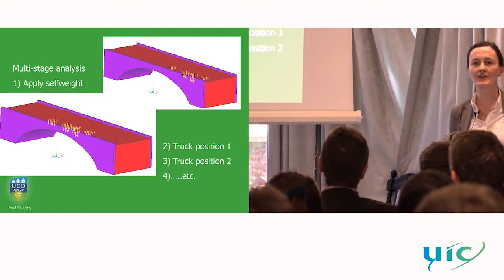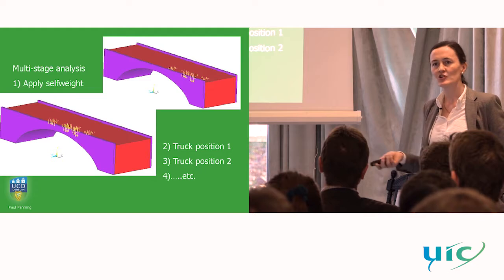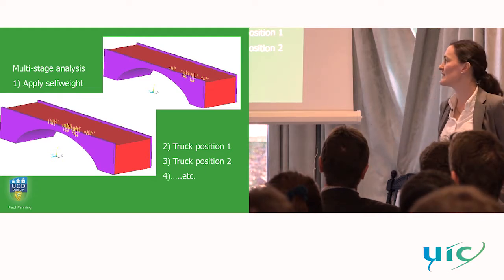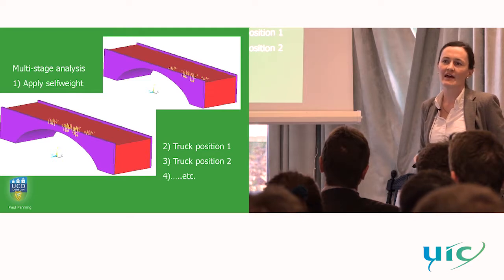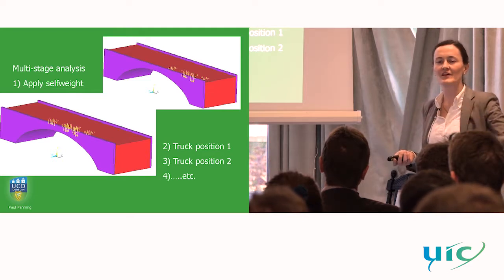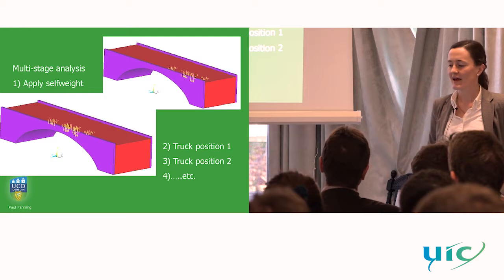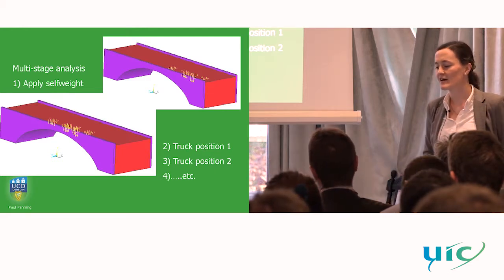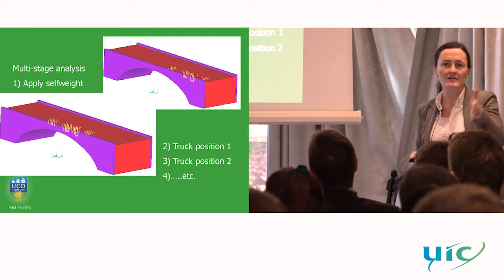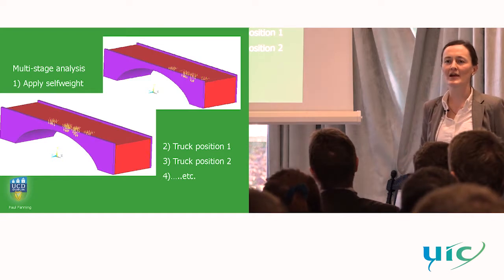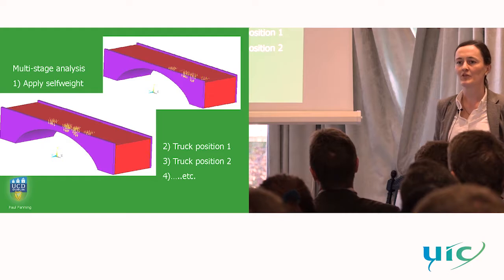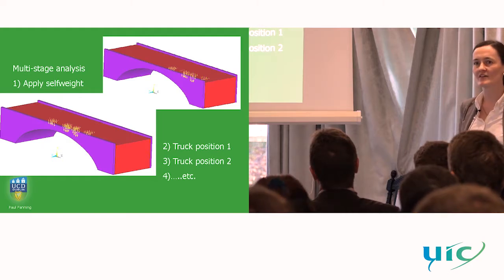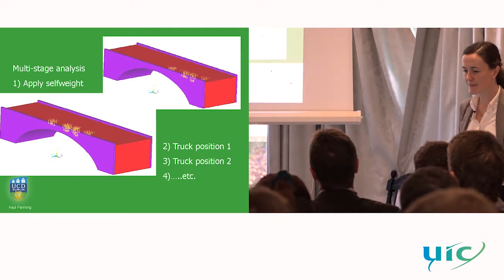For our service load simulations to correspond with the testing that I'm discussing here, that was all carried out at quite low speeds. And so the approach that we've taken here is basically a semi-static modeling approach where we're just incrementally moving the loads as opposed to conducting a transient analysis.